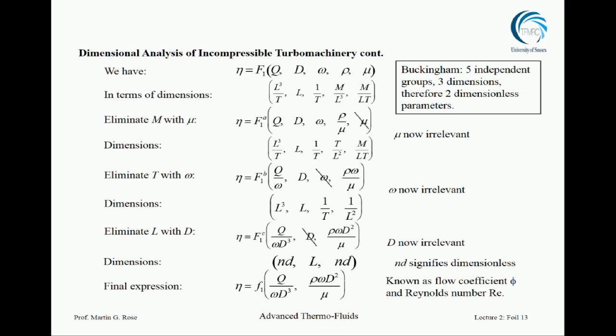No, the simple thing is that in Reynolds number we're used to seeing a velocity. There's no velocity in this equation, but there is omega times d. Omega is the rotational speed, d is the diameter, so the velocity is hidden in there, and then times d again, it's d squared, which is what you expect to see in a Reynolds number. So this is a perfectly genuine Reynolds number, it's just written in a slightly funny way.